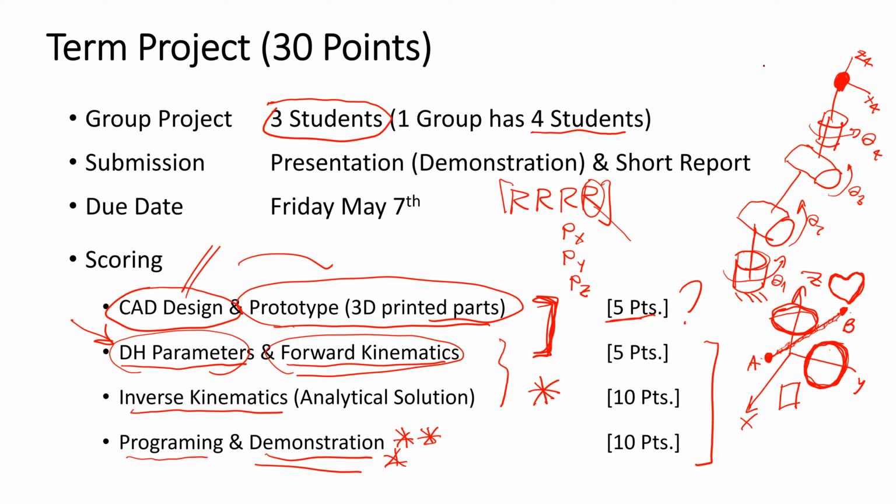But if you see this robot, if you put the last link like here, the last joint, the joint 4, it seems like the rotation of the joint 4 cannot make any meaning to the position at the end effector, cannot make any meaning to px, py, pz at the end effector.